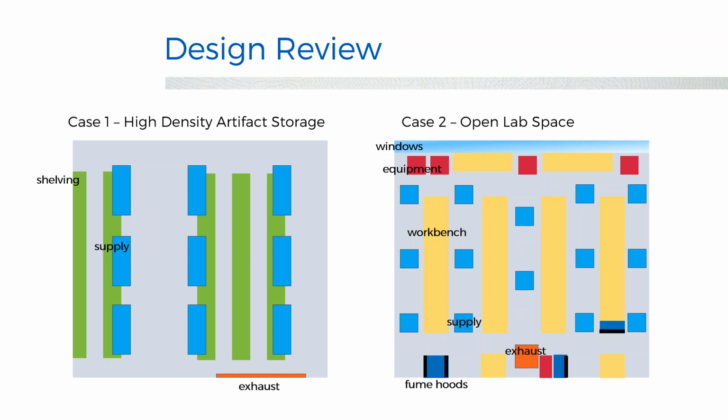And if you're going to investigate the performance, you might as well see if you can go down to a lower air change rate, because chances are if you solve your problems, it's likely that those drops will also be beneficial, and then you'll be saving not only energy but also cost on the amount of air and cooling. Makes sense. Okay, we have another question.